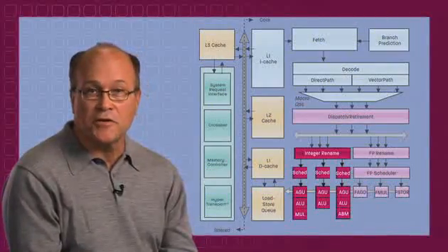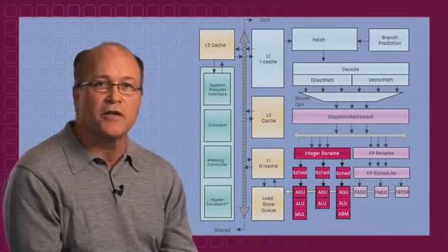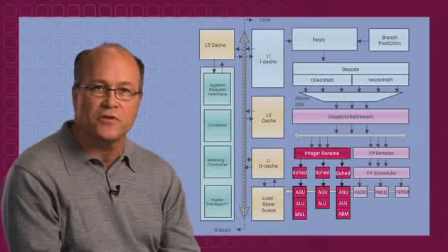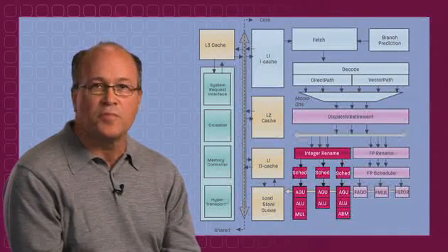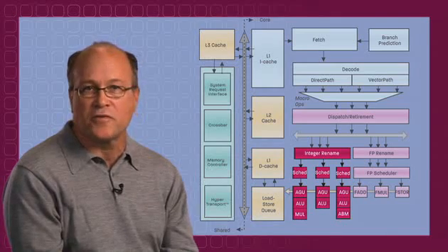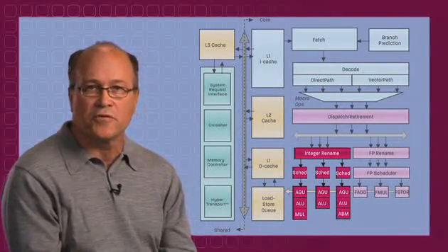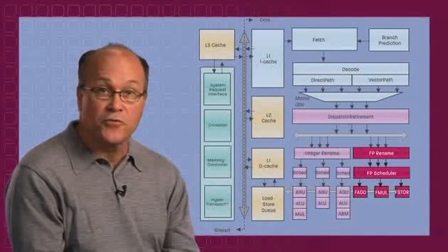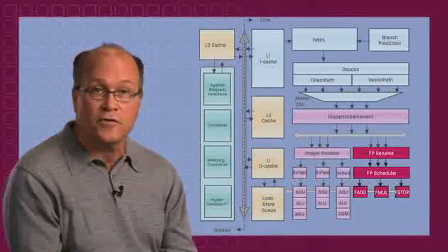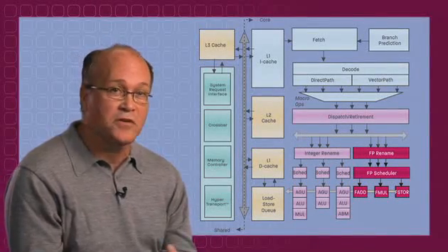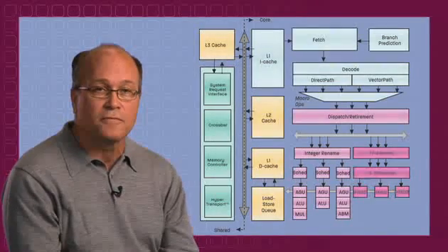The superscalar integer unit significantly speeds processing. Our 12-stage pipeline is one stage longer than our second generation AMD processor. This is a 3-issue processor, so based on this architecture, most processing is arranged in triplets. When dealing with instructions, we have 3 decoders all the way through. Our superscalar 3-way floating point unit is also super pipelined. It's 128 bits wide, which means it can achieve 4 or 8 flops per cycle, double or single precision.